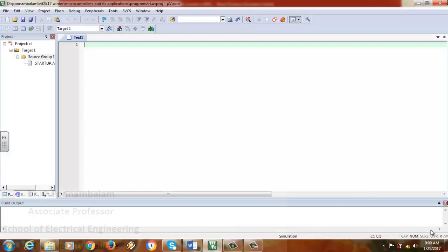First we'll have to initialize the memory address of the internal memory: MOV R0, #50H. So this is the internal memory address I have initialized in R0. Then the external address I'll initialize in DPTR, #4500H.